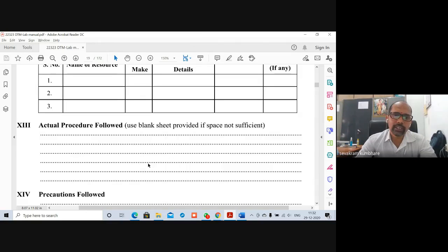Then we connected input 1 and input 2 to the input pins through the slide switch. The output pin is connected to a resistor and LED. Then we started the simulation, applied input, and noted down the voltage and LED status. Got it? Can you write it down?